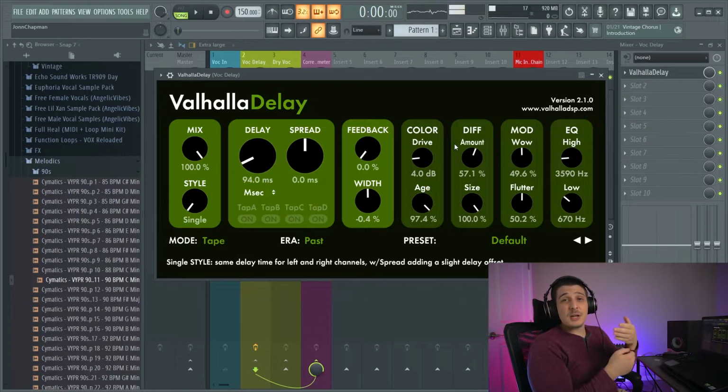The tape could sometimes get hung up on something as it was pulling around it, if it wasn't clean or just in general, which would cause some drag, which would cause it to go through the delay slower. And the way this translated into how the high and low frequencies were put onto the tape and then later played back created what was called wow and flutter.